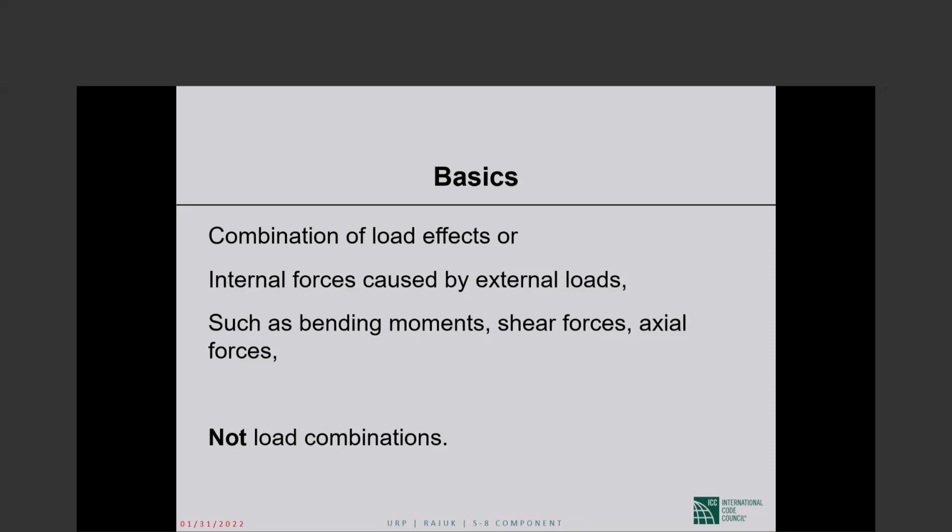So do wind forces. Wind causes bending moments, shear forces, axial forces at various critical sections of various structural members. Those bending moments due to dead loads, live loads, wind loads can be combined. Those shear forces due to the various loads can be combined. And that's what we do in design.